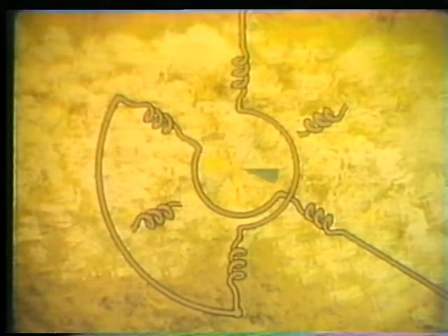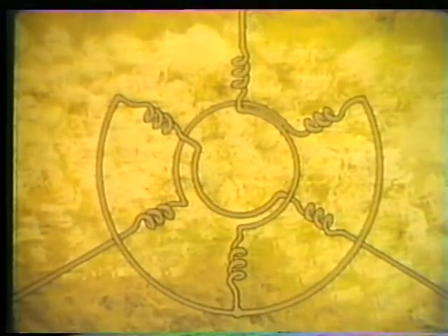Now, watch what happens when the third coil pair is energized. Because the third phase current is generated 2/3 of the way into the first phase cycle, the magnetic field generated by each coil pair differs in intensity. The magnetic field between the stator coils, therefore, rotates.